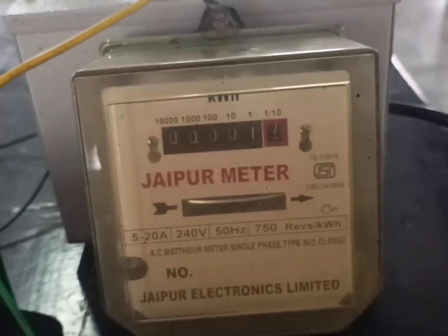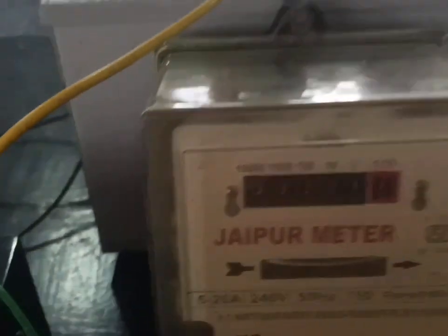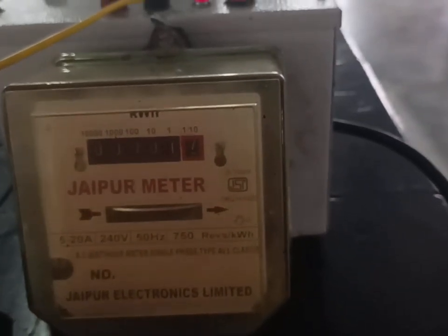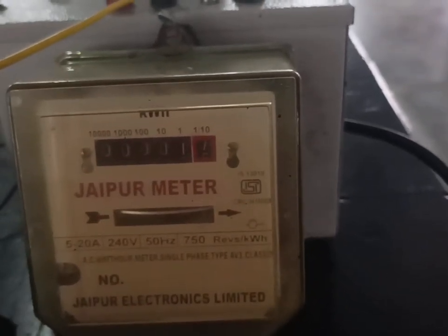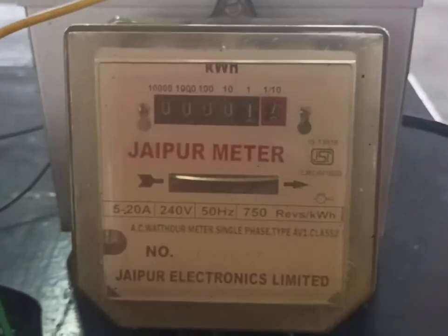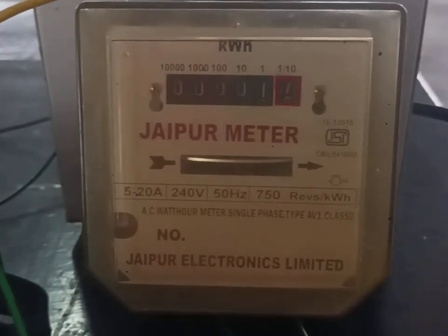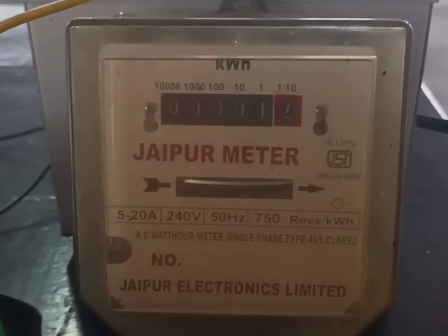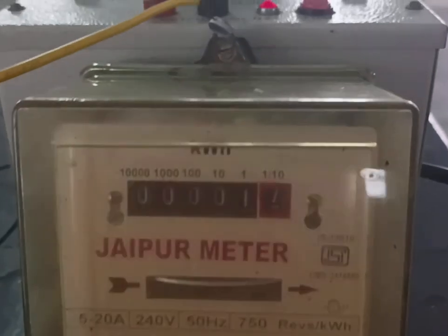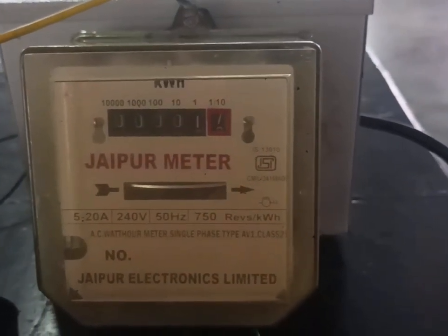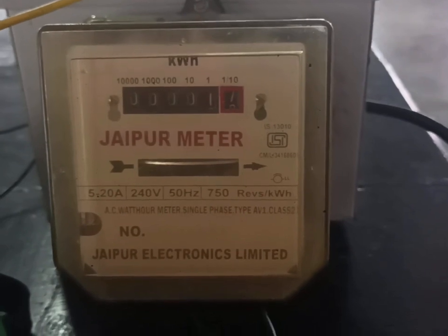This is the experimental understanding. In conclusion, when the load increases, the watts and amps ratings increase, the energy consumption and energy meter disc rotations also increase, and only the voltage rating drops. When the load decreases, the watts and amps ratings drop, the voltage gradually increases, and the energy meter disc rotation speed drops. This is the conclusion of this experiment.